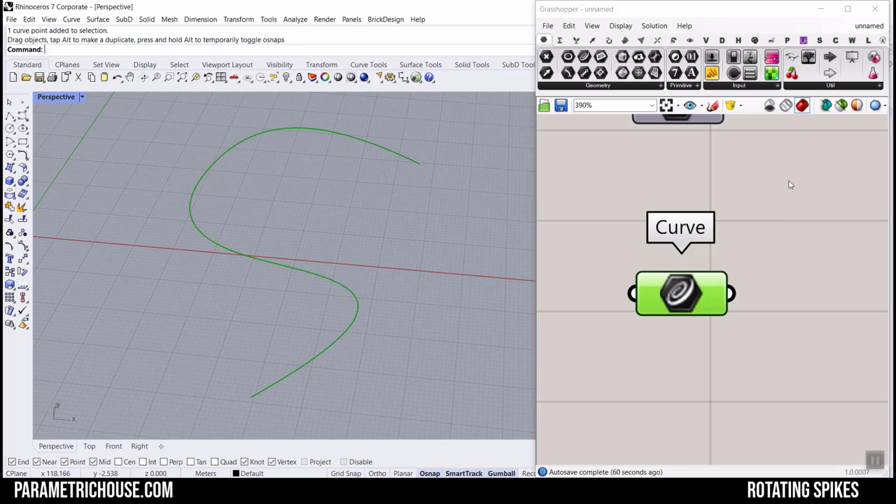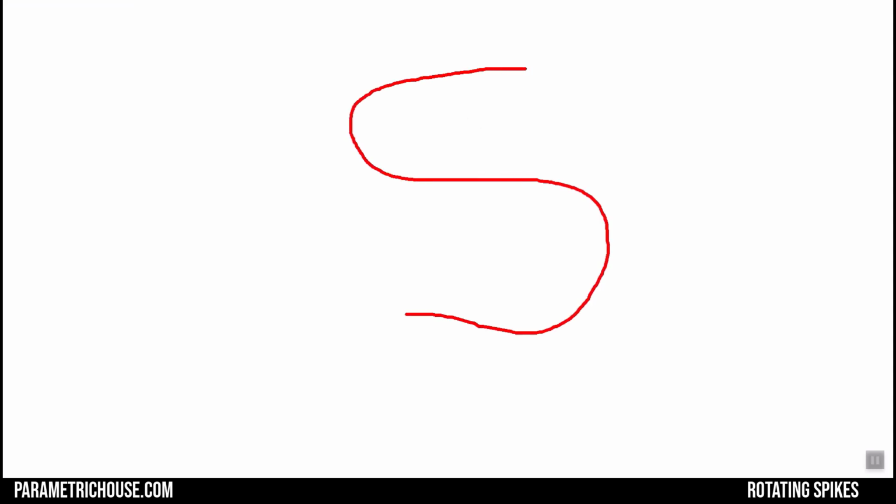Okay, before we go to the pattern, let me explain what we're going to do in Grasshopper. First of all, assume that this is the base curve. Okay, we're going to extract the perpendicular frames. So we're going to use perpendicular frames to extract it. If you don't know about this one, we have a short lesson about perpendicular frames. I'm going to put it up here on YouTube so you can check it out. Okay, then we divide the curve into perpendicular frames.